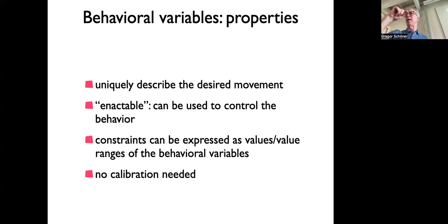For instance, they might have a simple black-white pattern somewhere inside, and there's a photoreceptor that counts how many changes from black to white you have, and that tells you, digitized, how much the wheel turned per second. And there are other ways to do that as well. Now, that part of how that's controlled we'll neglect. That will sometimes not work. For instance, if the wheel slips, then you make an error, right? And we'll have to see what happens then.